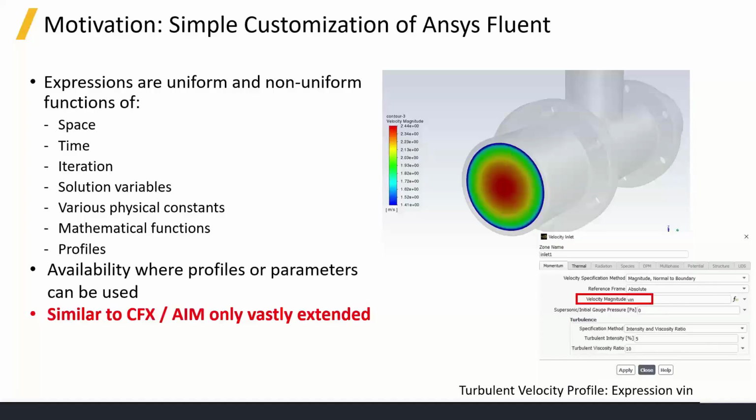We can use iteration in it to help us ramp things in or change things. And we can obviously make use of solution variables, various constants, functions, even profile data can be brought in and used. So anywhere where there's profiles or parameters pretty well in Fluent, you can now start using expressions.